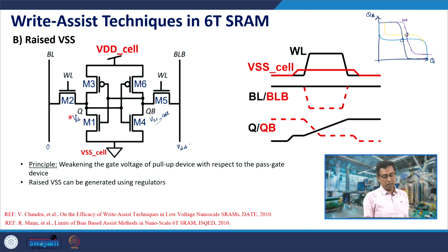The actual flipping would happen at a higher value of the metastability point. Q and QB both assume a higher value, and therefore you need to discharge Q to a smaller value. How much charge is to be taken out is now smaller. So, it would happen faster due to this reason also.